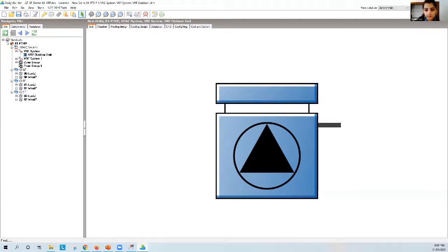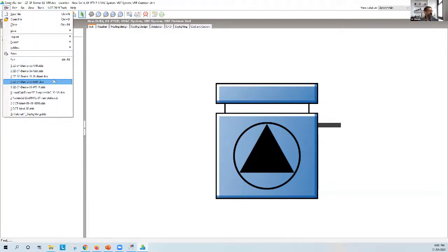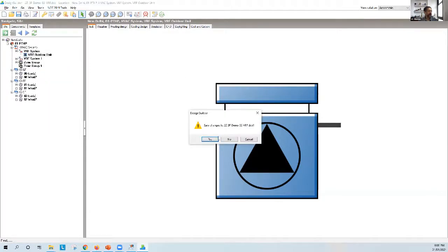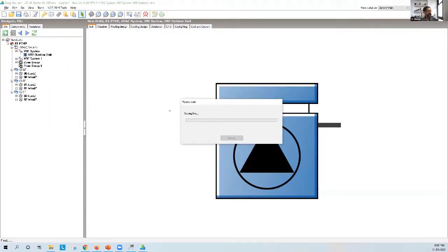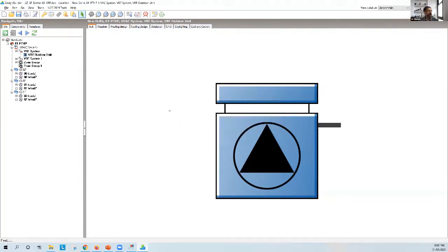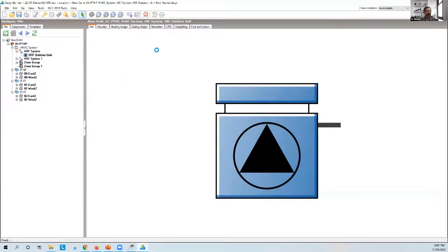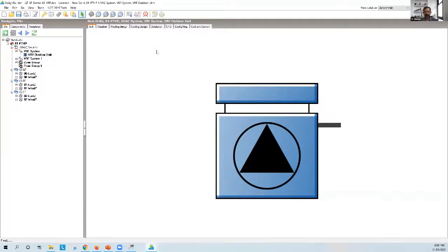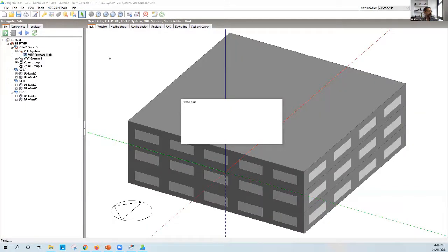Yeah. So because you're using the detailed HVAC systems, that is actually taken care of for you already. Let me pick up the chilled water system. All the curves that are attached to chillers already look after the part load performance. Okay, so I'll just show you.